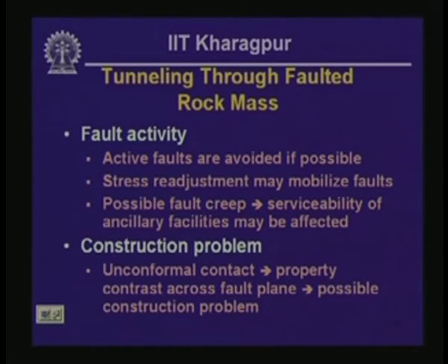The second aspect related to fault activity is that the stress readjustment because of the tunnel opening itself may mobilize faults, and that is indeed the case in very deep underground mining operations. It has been seen in many cases in hard rock mines which can go a few kilometers, say 2 to 3 kilometers, below the earth's surface.